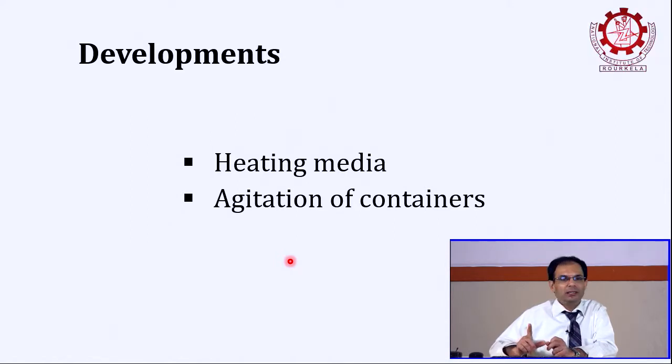So what does heating media mean? When Nicholas Appert really started, of course his experiment was with only hot water, but then later we learned what the problem with hot water is. You can have a maximum temperature of 100 degrees C at atmospheric pressure, right? Then when we learned that we need to use 110 or 120 degrees C plus, you need a pressurized vessel. Steam can give you temperature and pressure as well. So the steam retort became popular, and for the next 150 years it was steam retorts all around the world.